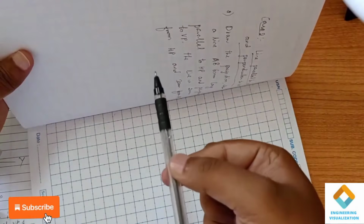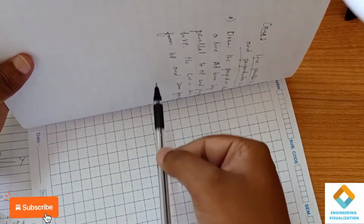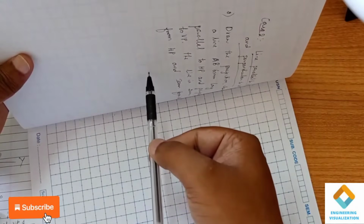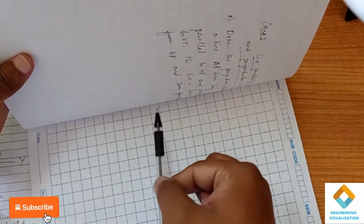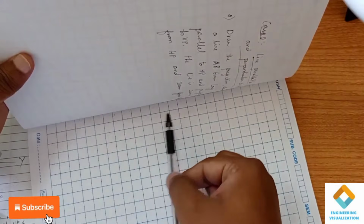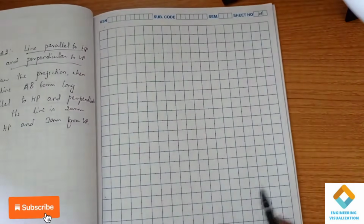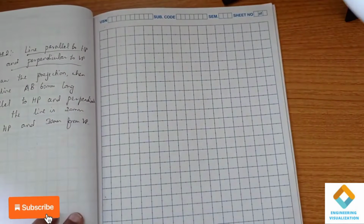This pen is parallel to HP and perpendicular to VP. Perpendicular means you will get a dot on the vertical plane, and there is a straight line in the HP plane. So this is parallel to HP and perpendicular to VP. Like this we have to do. So first we are going to draw an XY line.